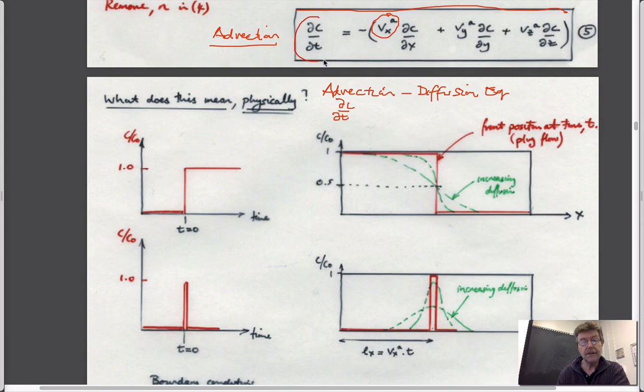In other words, the left-hand side from both of these equations, and I'm going to write just three terms, is equal to the diffusive part, which we call D star, multiplied by the change in concentration with space, and minus this expression here, the advective velocity multiplied by the change in concentration with space. So, just so it's in one place.